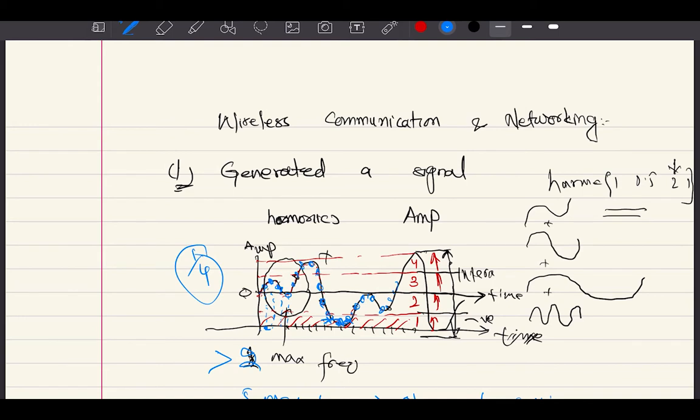And then there are plenty of other points located in this region, and they belong to the second quantile interval. So all the quantile points will be allotted like this. This is the original point, and there is some difference between the original point's location and the quantization that is done by you, and that is called the quantization error.